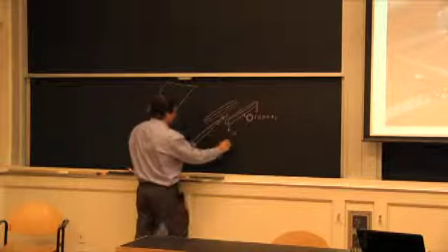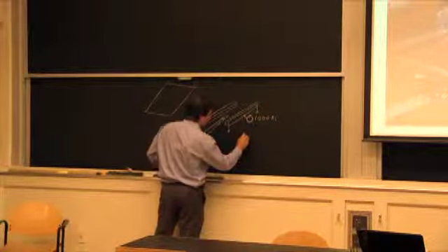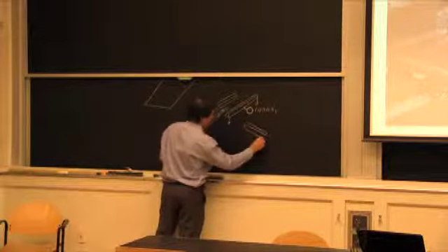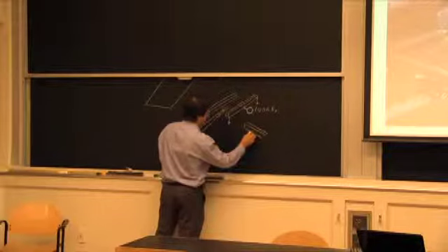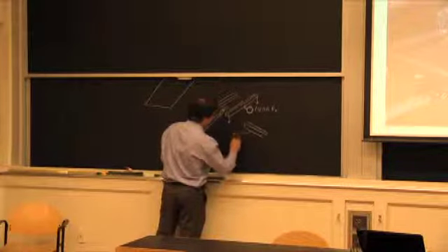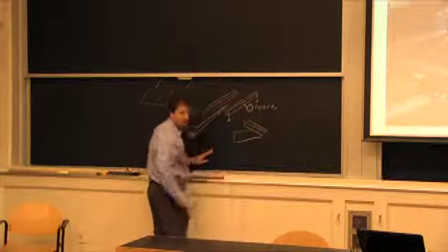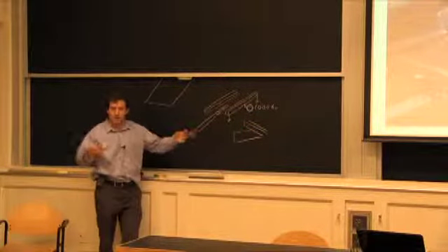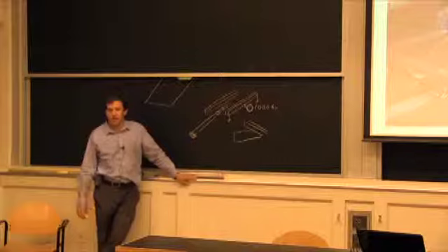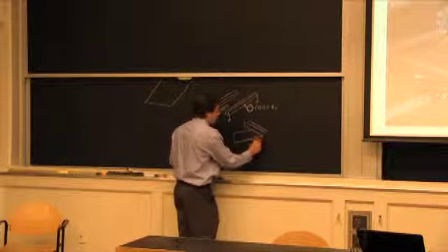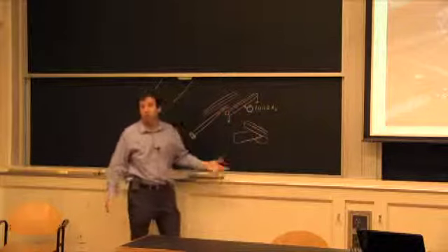So if I try to draw it, it'd be the cross member coming, and well, let's do it this way. So it'd be coming right under and being welded together there, and on the sides. There's some stiffening plates there, but the idea is where I knew there was a risk of a tension yielding, there are no welds at all.